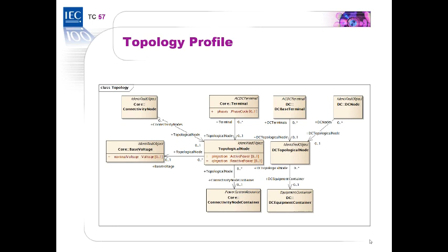We have fairly recently added HVDC to CIM, and actually also added a detailed node breaker model for the DC part. And the reason for this is we expect DC networks to come in the future. It's not here yet, but it's probably coming not that far away. So we prepared for that. And they are structurally identical.